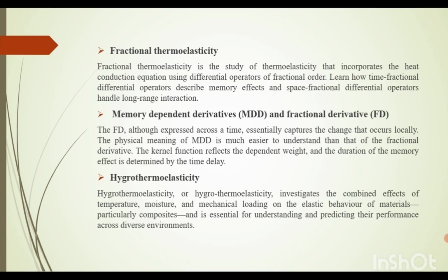In hygrothermoelasticity, the rate of diffusion grows very quickly with increasing temperature. Severe thermal aggregation caused by extremely high temperature that splits atoms and molecules apart may cause the material to melt or disintegrate. Concentration gradients may also arise as a result of uneven distribution of moisture. Heat transfer and moisture transfer are basically the same processes, and they might or might not be discussed independently based on the surrounding conditions. Irregular heat and moisture transmission through solids may alter the dimensional characteristics of structural parts, causing interior stresses and strain in high performance structures.